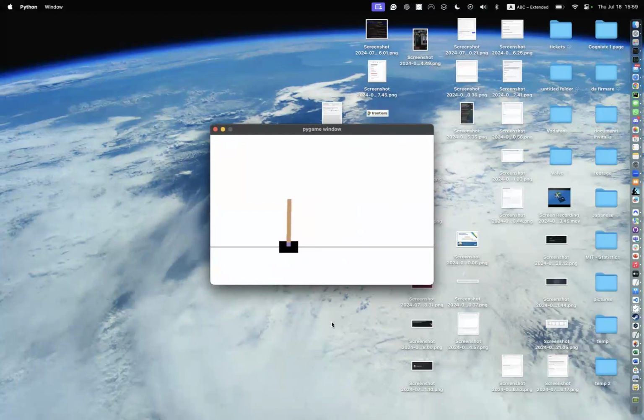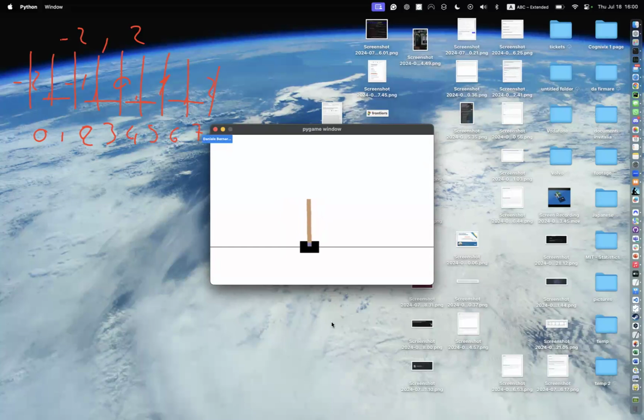So when you're discretizing, you're taking a continuous number. So let's say our position is -2 to 2, okay? Then I decided this, so -2, -1, 0, 1, 2. These are the limits. There is a unit here, a unit here, a unit here, and a unit here. And I want to divide it in 20 bins. Let's say I want to divide it in 8, okay, because I cannot write the rest of the 20. So what I'm doing is assigning a value here that is 0, 1 that is here, 1, 2, 3, 4, 5, 6, 7. And then these are the digits. That's why it's called digitize.